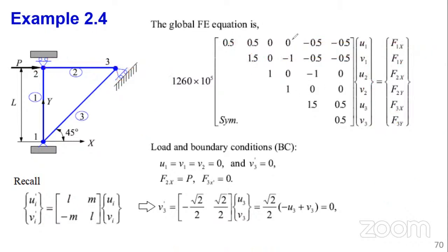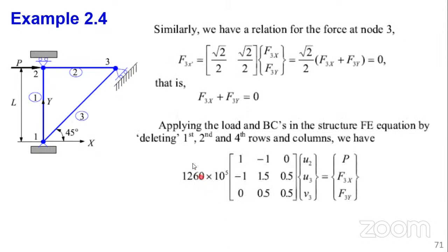So once you do that, it is now just a matter of solving it the same way we have been solving for the others. So you apply the boundary condition, you delete those rows and columns associated with 0 displacement. So you have a very simplified matrix. What we are doing is invoking boundary conditions because we are solving a boundary value problem. Without boundary values defined, we have not clearly defined our boundary value problem. Okay.